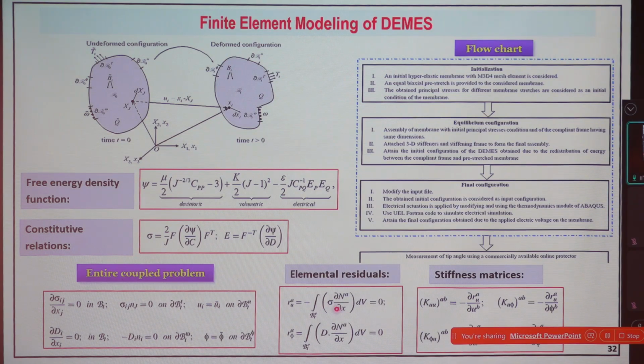By incorporating the shape function along with this, you will get the residuals in the electrical domain and mechanical domain. After using these residuals, you can calculate the stiffness matrices. So ultimately your finite element simulation is going to incorporate Ku equal to F, that basic approach. Okay. So it's a tedious process. I have one of my papers on this, where step by step you can understand how we implement this basic algorithm or formulation. This always remains the same. It is not going to change.